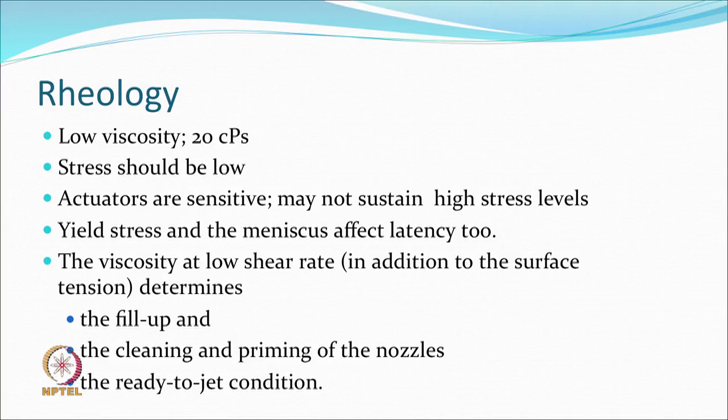Yield stress and the meniscus affect the latency. That means, whatever polymer system we are going to add will modify the rheology. Viscosity at low shear rates, in addition to the surface tension, determines the fill up. Fill up means whenever some volume goes out of the chamber, something must come back. Cleaning and priming of nozzles is also important.